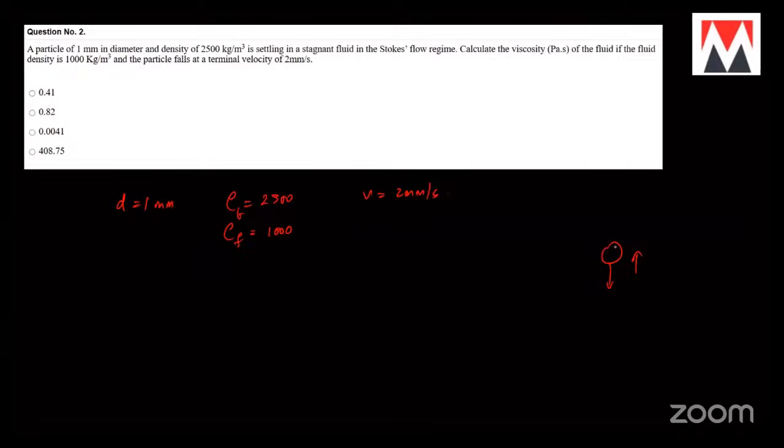So for this particle, you'll be considering how much fluid it displaces, which is the volume of fluid being displaced. So you'll have 6 pi eta R V is equal to 4 pi by 3 R cube into rho of body minus rho of fluid. This is the force balance which you'll have, with the buoyancy force.